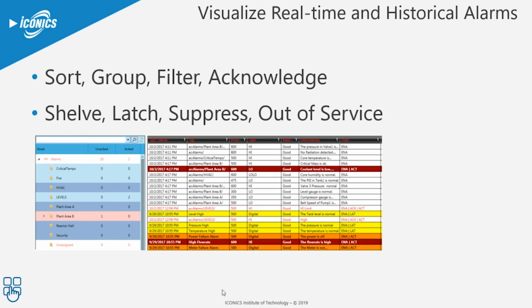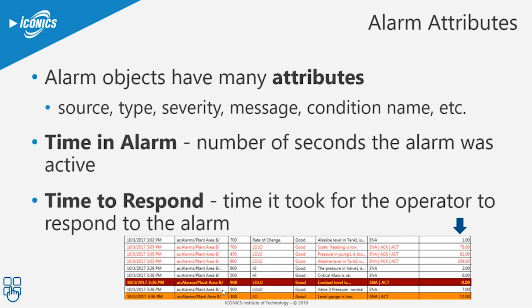The user can filter and group alarms, which is specifically useful to analyze all alarms for today or this week. Active alarms may be shelved if they do not need immediate attention. Each alarm may have attributes such as the timestamp, tag name, message, or process value, and the user that designs your alarm dashboard will decide together with you which attributes are relevant to see in any dashboard. Historical records typically contain more attributes to allow detailed analysis at a later moment.